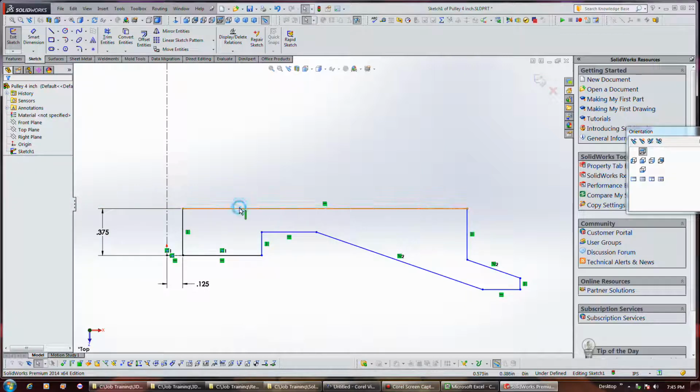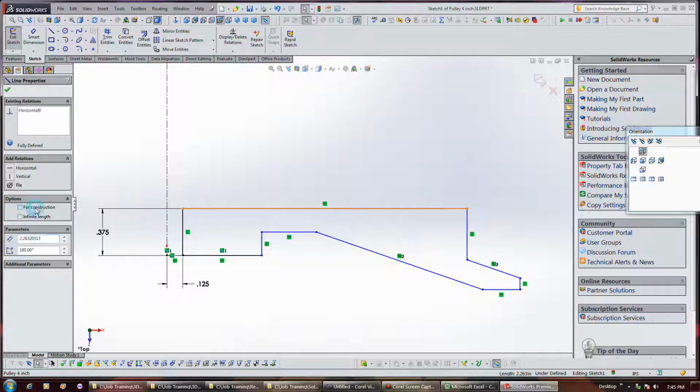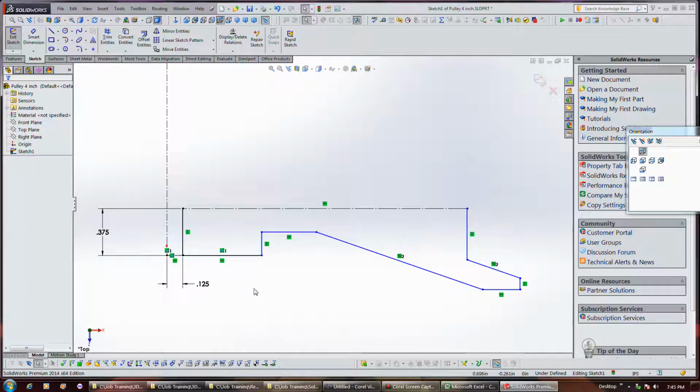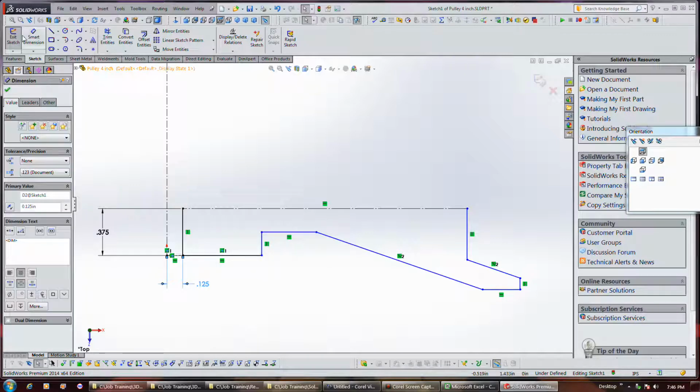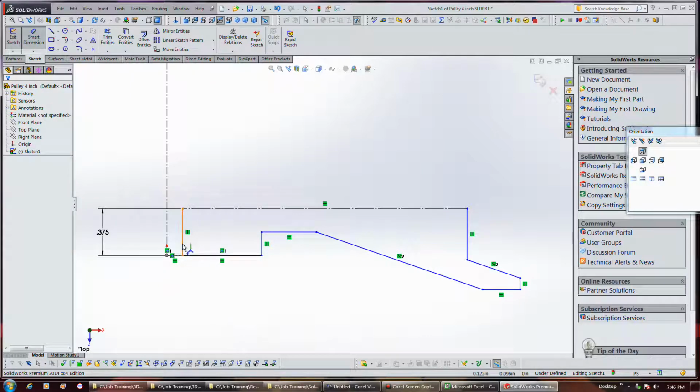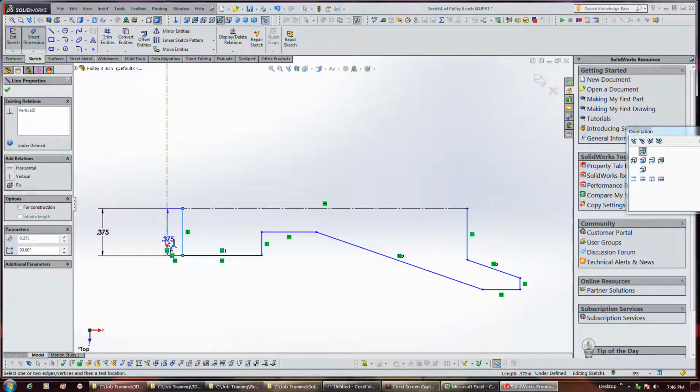Okay, I'm going to go ahead and click on this dimension and turn it into a construction dimension. Okay, apparently if you take a dimension like this and delete it, I can select it. Okay, but also select a construction line. And if I move it to the right of that line, you see on the right of the line, it's just a standard dimension, but it becomes diametral, for diameter. If I move it on this side of the line.